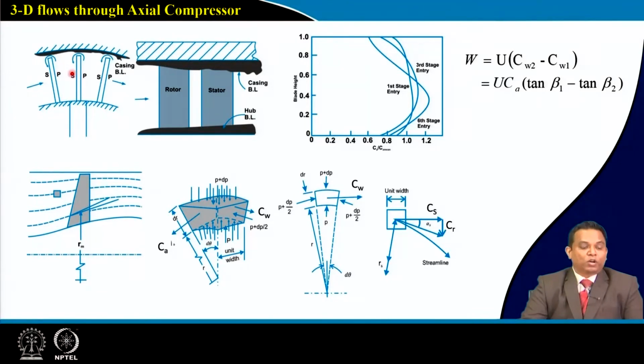Now we have also understood that in order to have free rotation of our wheel, we need to provide a certain amount of clearance between casing and our blade. This is one of the areas of research for many. Here, on my pressure side we will have higher pressure, on our suction side we will have lower pressure, and the rotation of the wheel is from suction side to the pressure side.